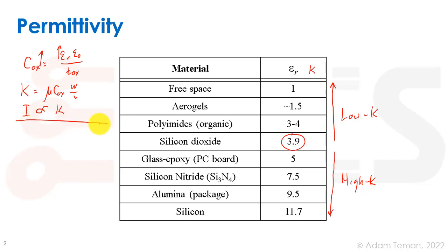The other reason is to improve our subthreshold slope, or our control over the channel. So if we remember, we have the gate, and then we have the channel over here, and then we have all kinds of other parasitic capacitances, which we called as a whole C dep, and this was COX, and we want to have COX over C dep be as high as possible, or we want to have N be close to 1. So we want to have as high a K as possible.